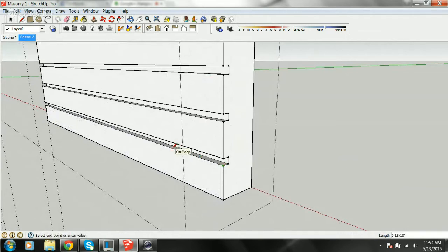Well, standard brick width is going to be 8 inches. Well, I'm not doing 8, 8, 8. I'm going to do 7.5 and a half-inch mortar joint. Now, the reason I'm using a half-inch mortar joint, and this is trial and error. I haven't sent one of these off to Shapeways to print yet, but when I calculate their minimum engraving detail, when I'm working at full scale here, what I've determined is that a half an inch is about as far as I can go down and have it be engraved.